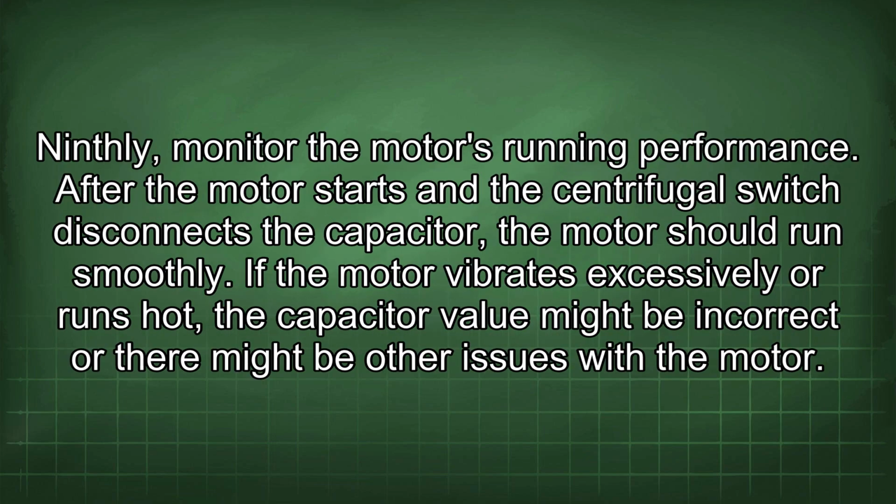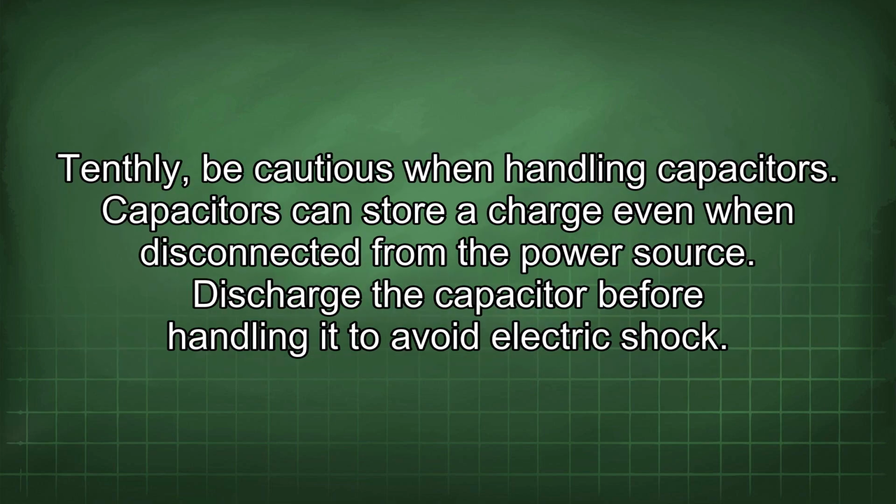Ninthly, monitor the motor's running performance. After the motor starts and the centrifugal switch disconnects the capacitor, the motor should run smoothly. If the motor vibrates excessively or runs hot, the capacitor value might be incorrect, but there might be other issues with the motor.